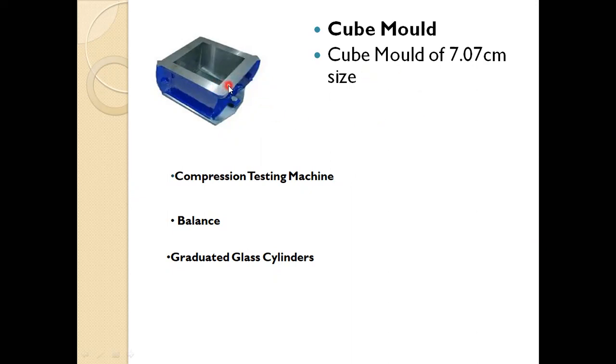For the cube obtained from this mold, we have to oil all the inner surfaces of the mold so that we can remove the cube easily.